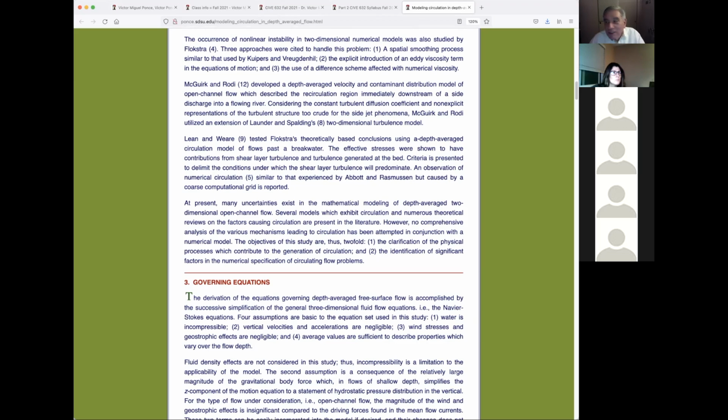McCarthy just said, this is the equation and this is the way it comes out. It was only Cunge 31 years later that said, actually, what McCarthy did was to solve the kinematic wave, only that he introduced numerical diffusion, and we can now calculate the numerical diffusion, and here it is. So that was a contribution of Cunge, giving the McCarthy method of Muskingum a physical basis.